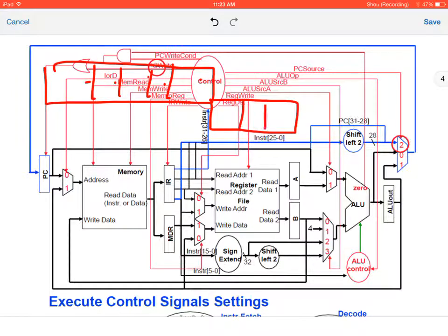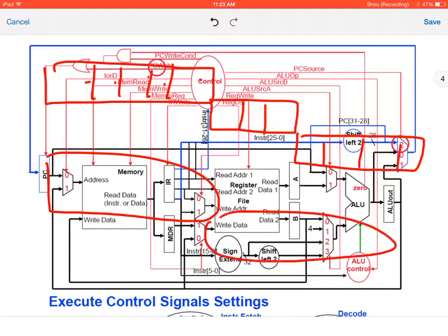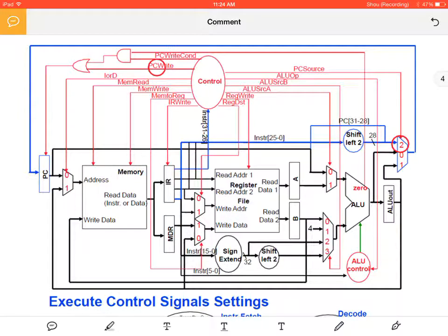We're using the finite state machine to lop off those last 2 stages. And then, in addition, takes 4 because we don't want to worry about data memory because we're not writing to the data memory. So this would be 4. So the difference here, this would be 5, this would be 5, and this would be 5. So single cycle would be longer than multicycle, but the multicycle has less area overhead than the pipeline. Okay. Does that make sense to everybody?